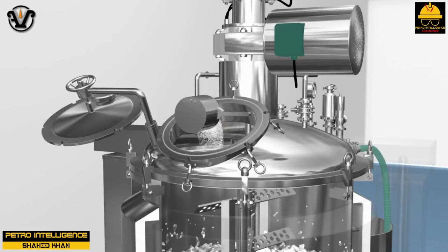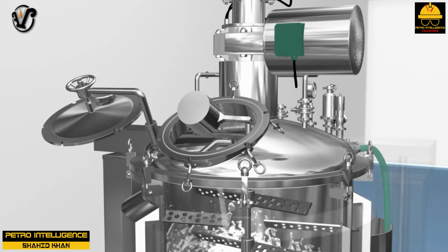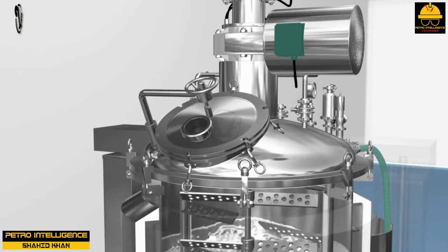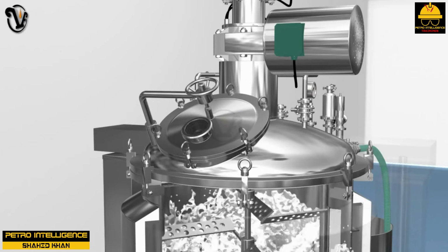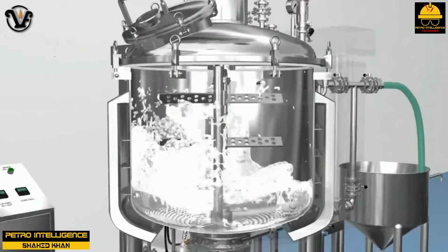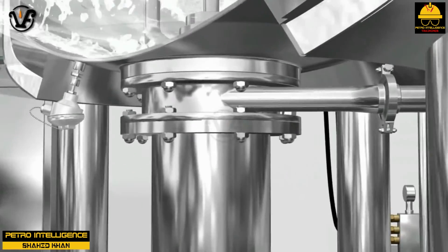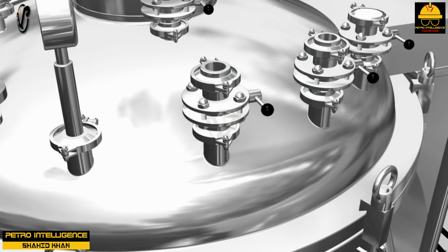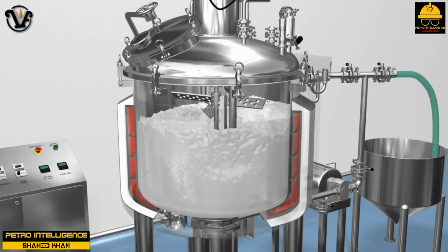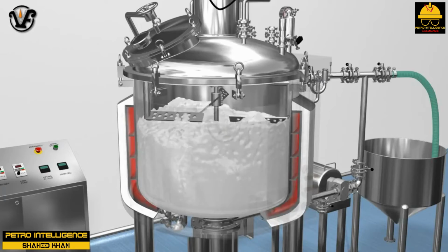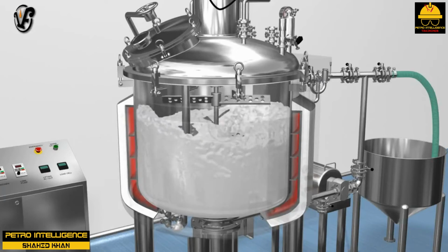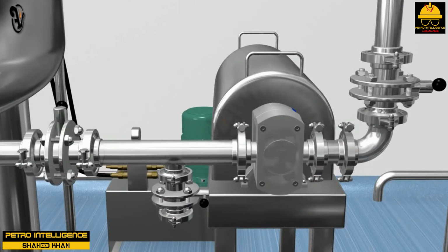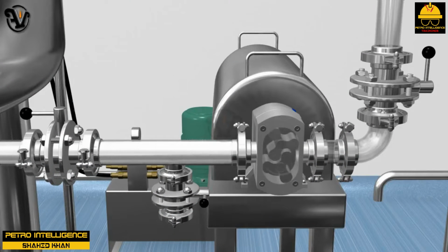Stirred tank reactors are used for liquid-liquid reactions, gas-liquid reactions, and liquid-solid reactions. Stirred tank reactors are used for reactions that require a relatively long reaction time and for reactions of slurry or thick liquid in which mechanical agitation must be used to provide a uniform reaction mixture. Such reactors are also used when the production rate is to be variable and several different reactions or products are to be made in the same reactor. The early research and development of most processes is conducted in batch stirred reactors because of their versatility.